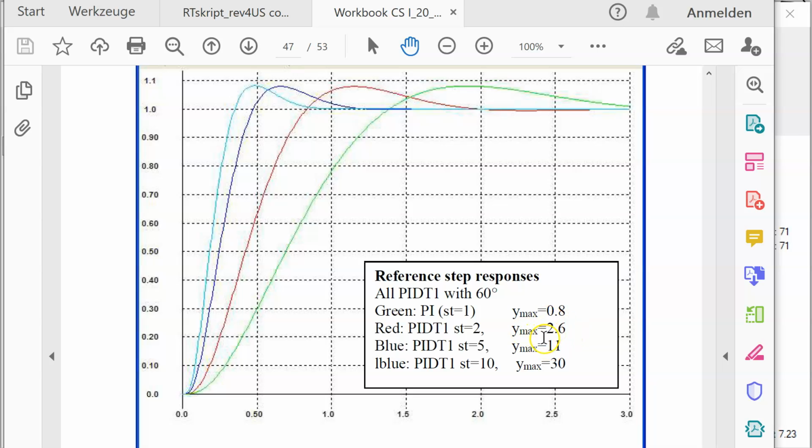In the limitation case, note then you get nonlinear effects like wind up, and you have to work with anti-wind up mechanisms, which are only really well available in digital control systems, not in analog realizations.